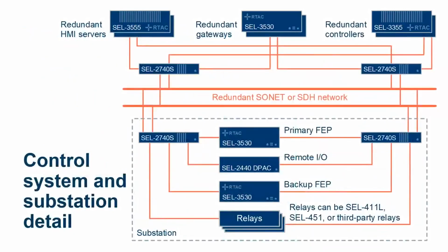At the substation level, there are local relays that act as contingency detection and mitigation devices that communicate to the local front-end processor, which in turn communicates this data to a centralized controller to make a more informed decision. This way, the RAS is designed in a modular and scalable approach. In case of a localized RAS, these local protective devices, or detection and mitigation devices, can also act as controllers.